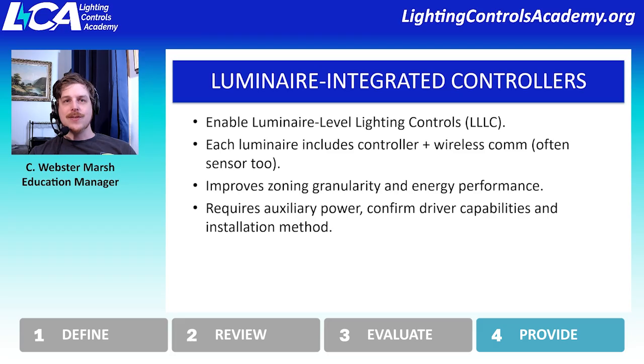There are a lot of considerations for triple LC, including having auxiliary power, which oftentimes is dependent on the driver. And in most cases, standard 0 to 10 volt drivers will not have that auxiliary power. So it's important as a specifier to make sure that the light fixture actually has the correct driver to be able to provide a triple LC application, because not all triple LC controllers are provided by the same manufacturer of the light fixture. It might be done through OEM, original equipment manufacturing, which means that the manufacturer of the sensor or the triple LC module will ship that device to the light fixture manufacturer, and the light fixture manufacturer will install that device.